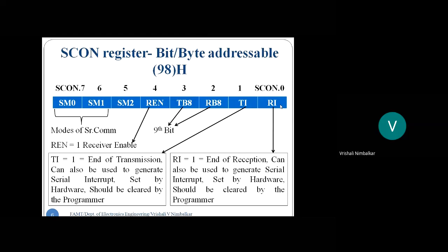So whether the microcontroller has completed that operation or not, the checking can be done in 2 ways, either using the polling technique or using the interrupt technique. Polling is checking with the help of instructions. Interrupt is activating that serial interrupt.